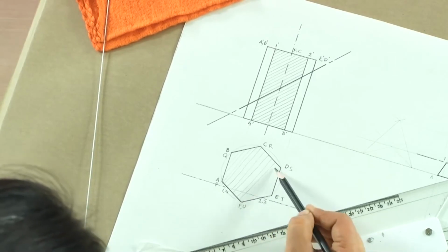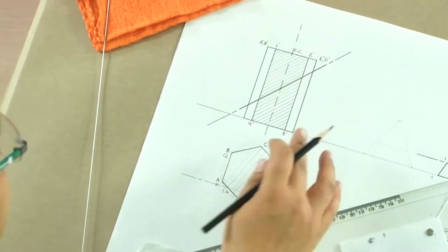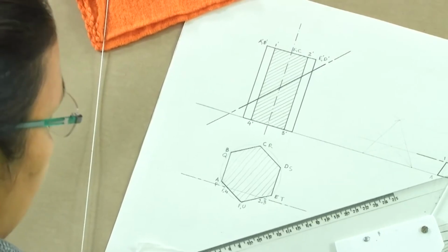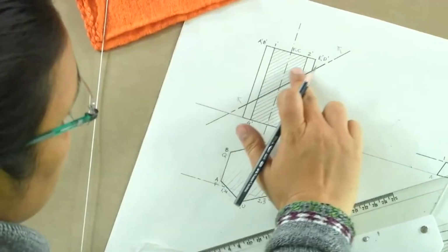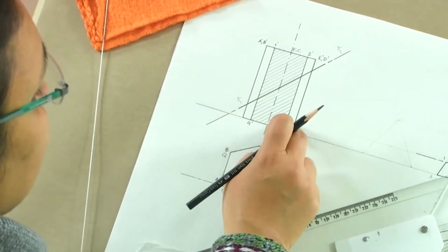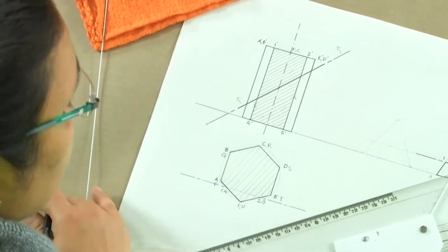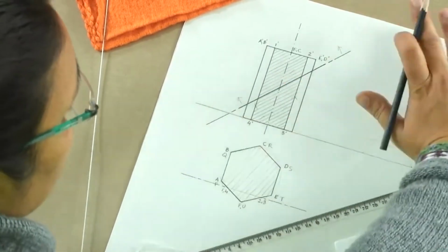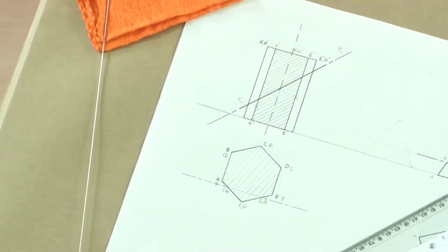So, this is going to be the top view of the prism. The remaining portion on the top of this section plane to this side is going to be taken off. So, this will all become light and we will only darken the portion which is below. These two lines are not there, the sectional hatch is not going to be there, and we will only be seeing the edges intact, and there will be a section line assuming the top portion is cut.